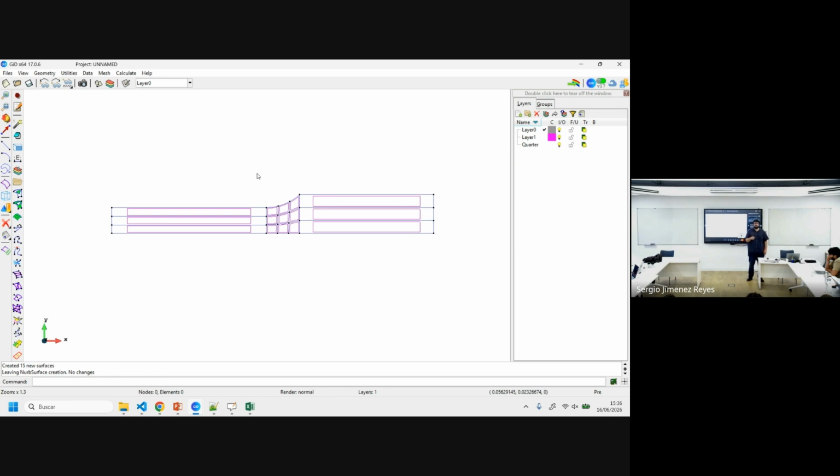And this is the reason why the kind of input that you will be introducing in your model to calibrate this hardening part of your curve, the values that you will be inputting there will be pretty much the same as the values that the experimental guys obtained during the experiment. Because what they are giving you, these engineering stresses, what are these engineering stresses? These are forces, they impose force by the machine over the initial section. Okay, this is our engineering stresses.